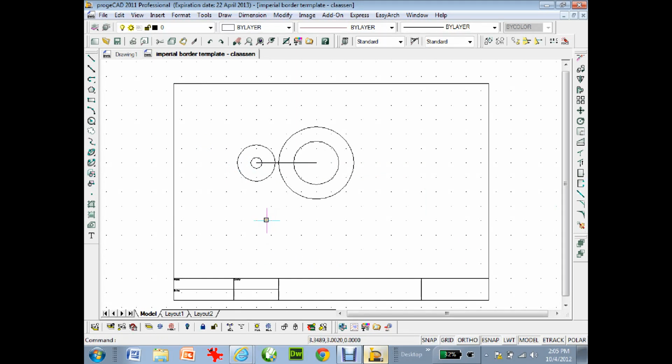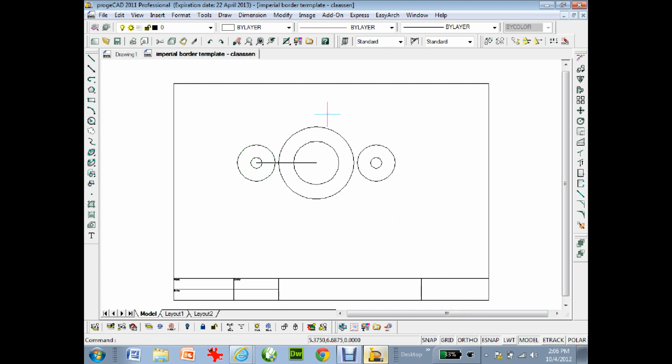There's that circle. Now, I could go to the other side and redraw them, or since you've learned it, mirror. Grab that object and that object, right mouse click. My start of my mirror line will be the center of the circle, and I'll just flip over. Now, I'm going around like this, so if I turn ortho on, now it just automatically goes there. Delete the original entity? No. There I am. There's my circles now. Okay?